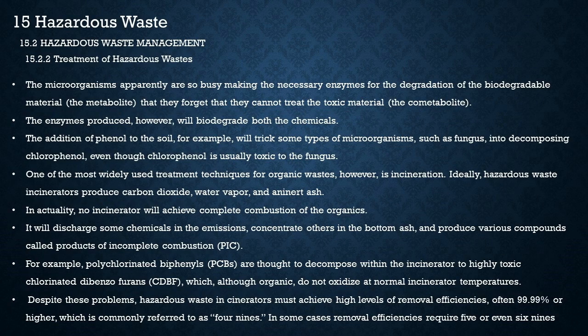The microorganisms apparently are so busy making the necessary enzymes for the degradation of the biodegradable material, the metabolite, that they forget that they cannot treat the toxic material, the cometabolite. The enzymes produced, however, will biodegrade both the chemicals. The addition of phenol to the soil, for example, will trick some types of microorganisms, such as fungus, into decomposing chlorophenol, even though chlorophenol is usually toxic to the fungus.